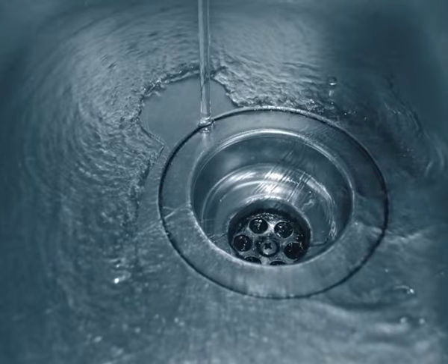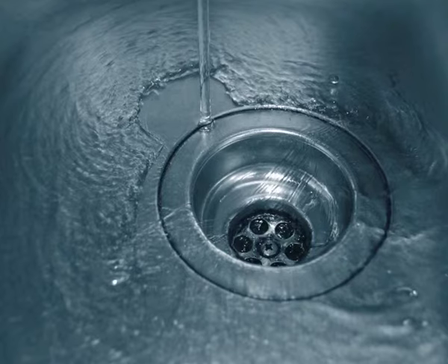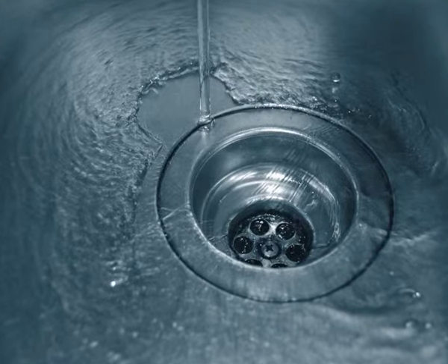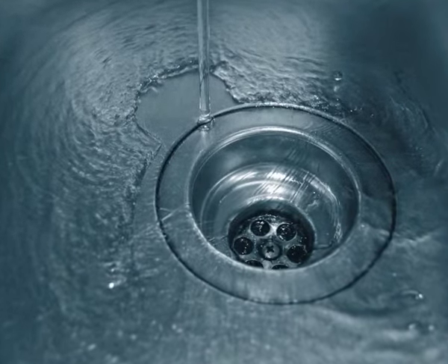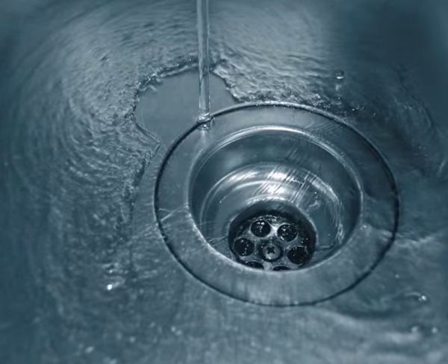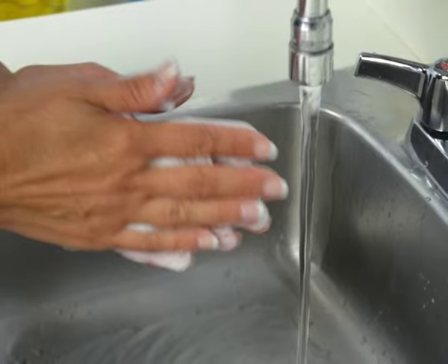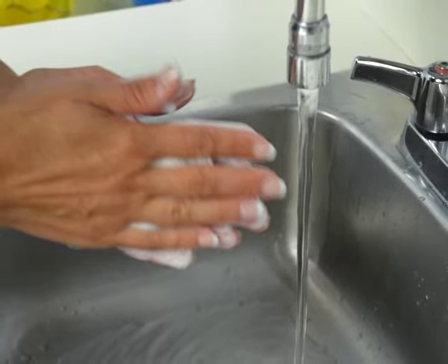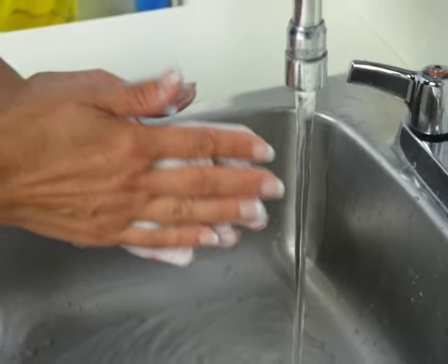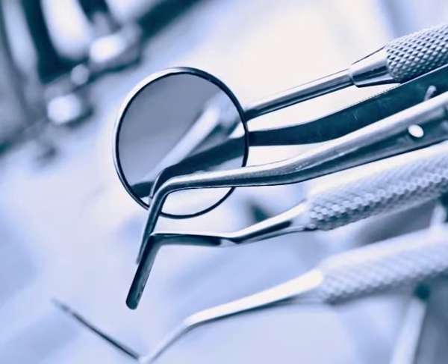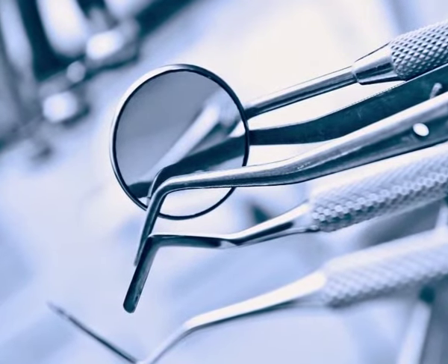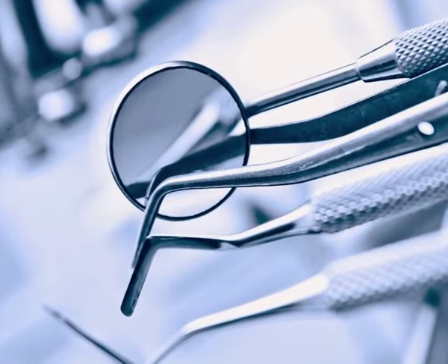Drains are considered inappropriate for classified areas of the aseptic processing facility other than the class 100,000, which is an ISO 8 area. It is essential that any drain installed in an aseptic processing facility be of suitable design. Equipment should be appropriately designed to facilitate ease of sterilization.